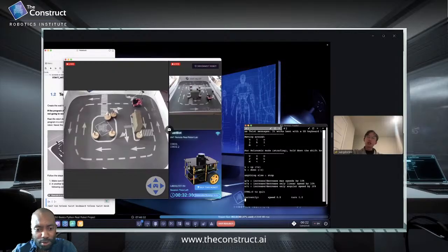We're probably going to look at it anyway after we execute it for the second time, but off the top of your head, what range of values or angular sector worked for you? I tried like 30, 40, but once the angle gets too big, it starts moving to the wall quicker than you expected, but you still want to make the robot find the wall.